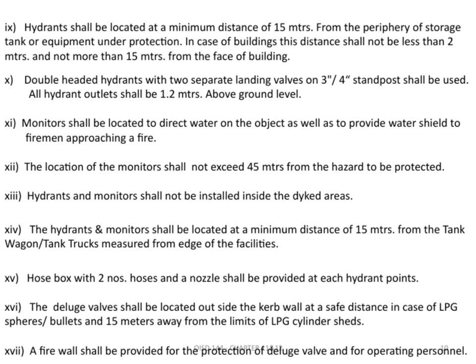and operational issues. Finally, hydrants should be located at least 15 meters from the periphery of storage tanks or protected equipment. In the case of buildings, the distance should be between 2 and 15 meters from the building face, ensuring both safety and accessibility. All these measures collectively contribute to a comprehensive fire safety plan, ensuring effective firefighting capabilities while maintaining safety for personnel and facilities.